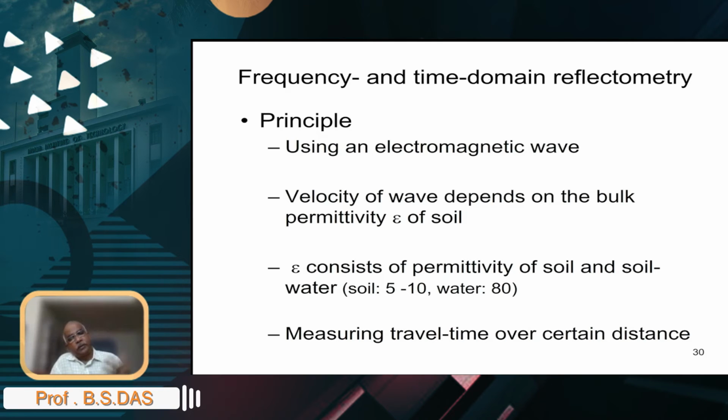generally these electromagnetic waveguides are used to allow the electromagnetic pulse to travel through those waveguides, and in the process, the materials surrounding in that electromagnetic field would show that polarization. So water mixture, where water gets polarized, and in the process you will be able to see a change in the overall dielectric permittivity, dielectric constant of the soil.